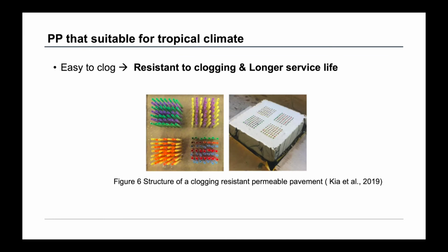Besides, clogging-resistant materials are more desirable because the sediments are more easily washed into the pores under higher rainfall intensity. Shown in Figure 6, the use of larger-sized materials in the surface layer or the use of sediment traps or additional pipes for drainage may decrease clogging.